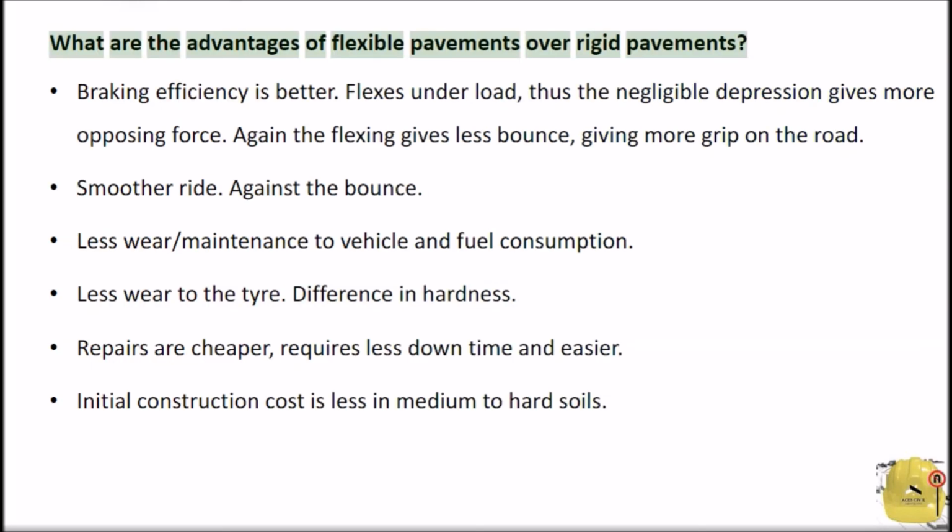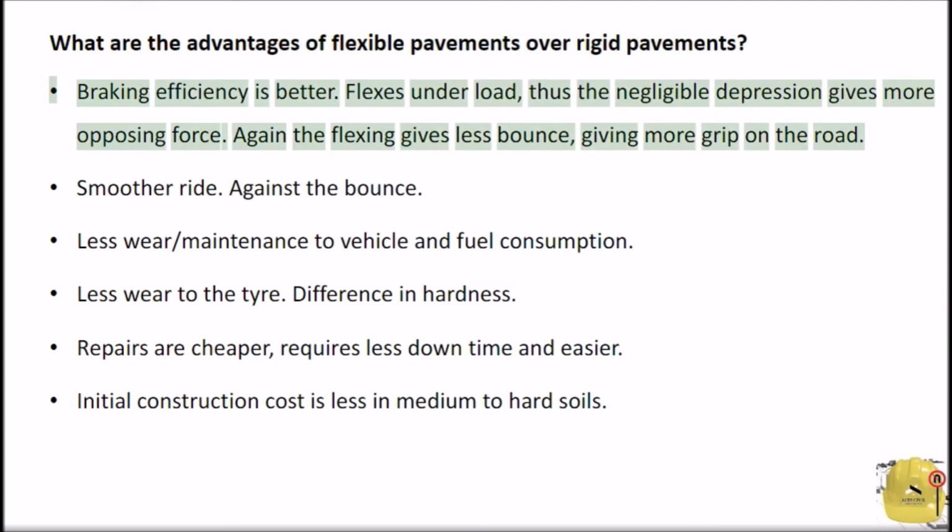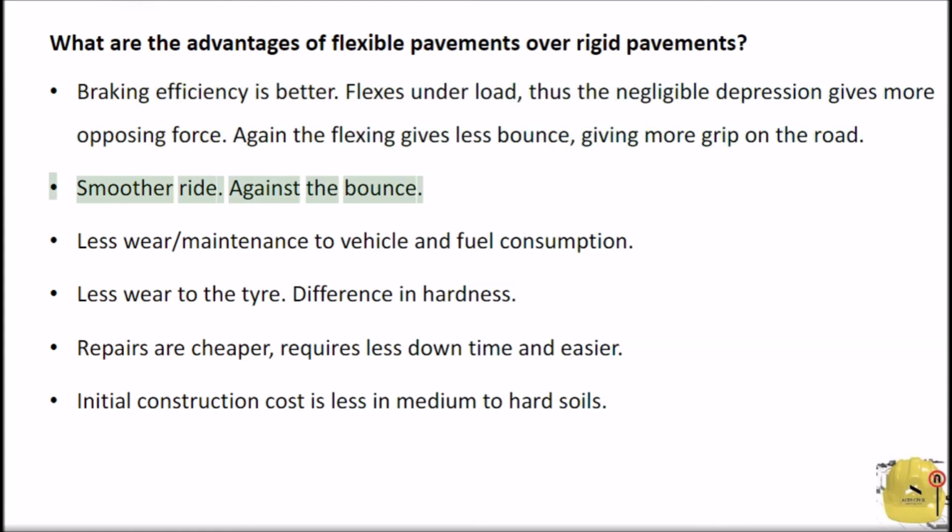What are the advantages of flexible pavements over rigid pavements? Braking efficiency is better. It flexes under load, thus the negligible depression gives more opposing force. Again, the flexing gives less bounce, giving more grip on the road. Smoother ride, against the bounce. Less wear and maintenance to vehicle and less fuel consumption. Less wear to the tire. Difference in hardness.